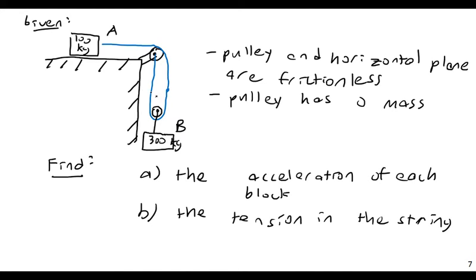So if I pull this down by, one way to think about this, you don't actually need to do a lot of math to figure this out. If I pull this down by 1/2 meter, think about that. That means that this cord is going to increase by a length of 1/2 meter, and this cord is going to increase by a length of 1/2 meter, which means all of that extra length has to come from this piece here. So if this one increases by 1/2 meter and this one increases by 1/2 meter, this one has to change by an entire whole meter.